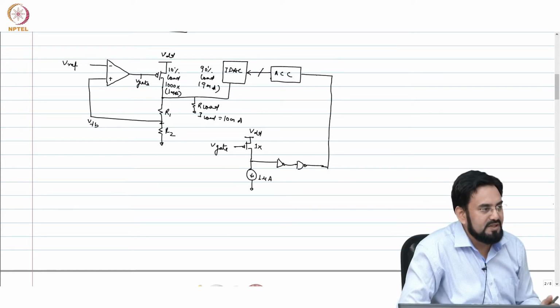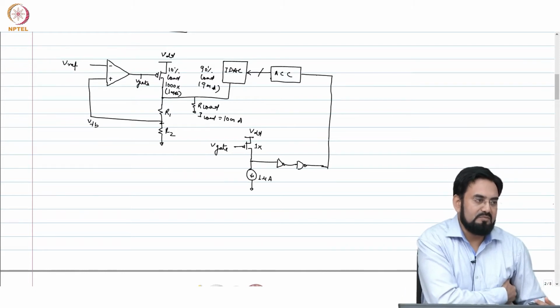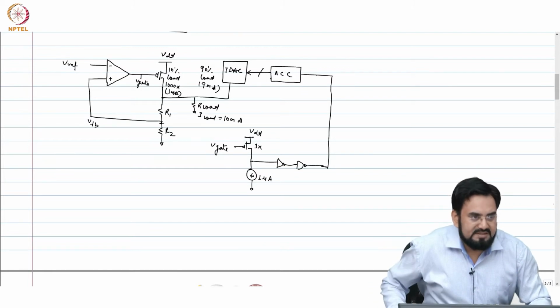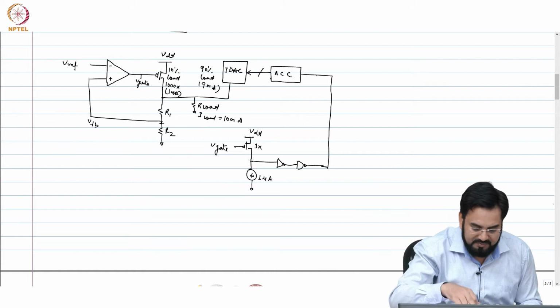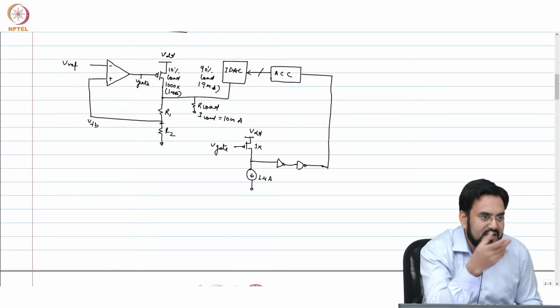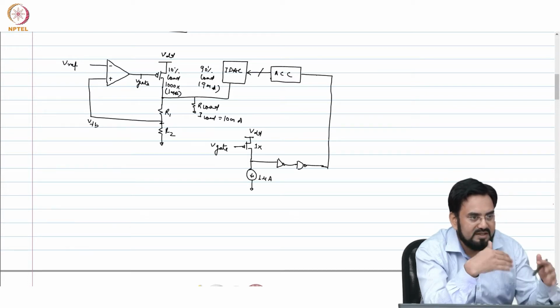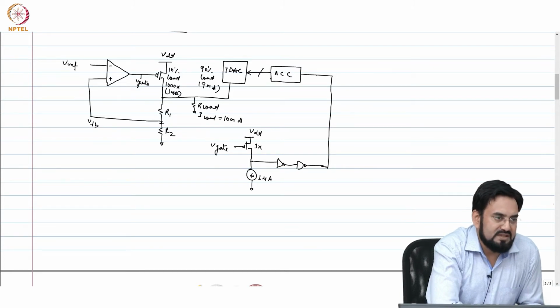If you want to make it 2 bit, you can define 2 current thresholds and make it your windowed comparator again. Okay, so let's say higher side you are increasing the code, or when it goes above 1 milliamp, lower side you can set at 0.9 milliamp. So you can keep a 100 microamp of hysteresis.